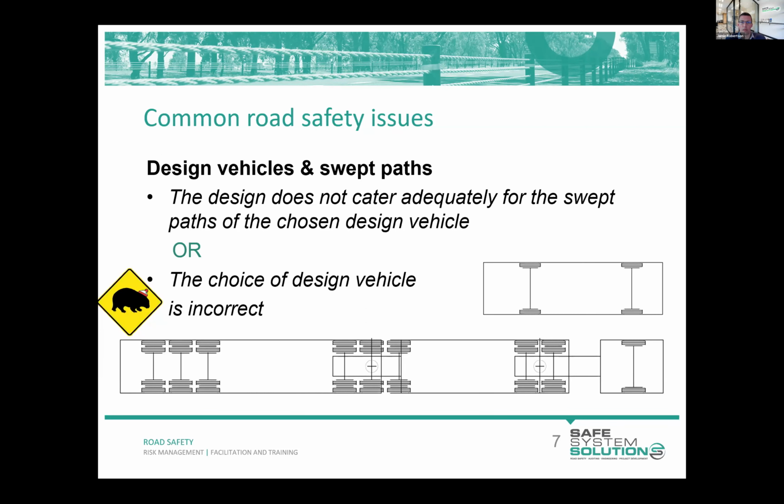And in that case, we might decide to pave behind the curb to accommodate that vehicle. Or it might need to swing out onto the other side of the road to make a turn, these types of things. But again, because it doesn't happen very often, we accept that. And it might be the case that the vehicle is under an escort or traffic management or something, so the risk is mitigated.